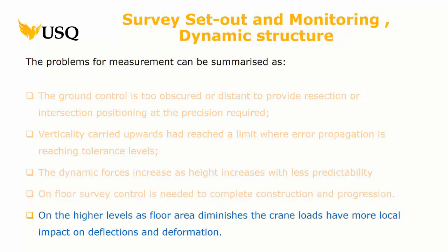Okay, and also as you get to a higher level, if you think about it from a physics point of view, the crane used at the lower level, right? The one you've got at the higher level is probably a bigger crane. It might be the same size, but possibly bigger because, number one, it's going to have a lot more wire because it's a long way up. And often you need different size cranes because they won't just use a 90-ton crane to pick up a basket of rubbish. It's inefficient. So the effect of the crane load at the top is greater, just for the sheer distance. It's just a bending moment.